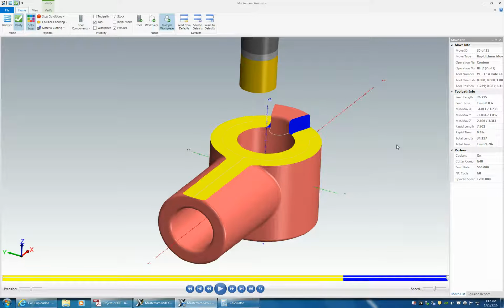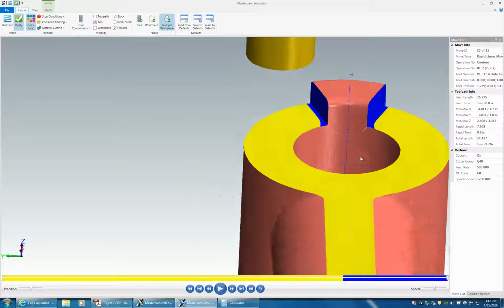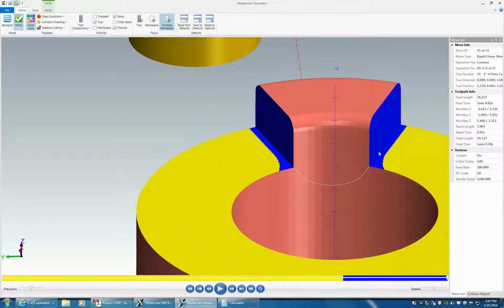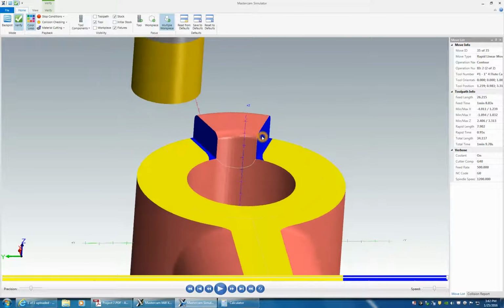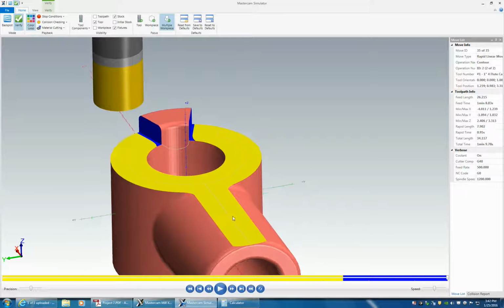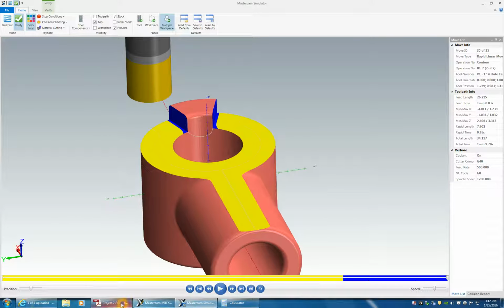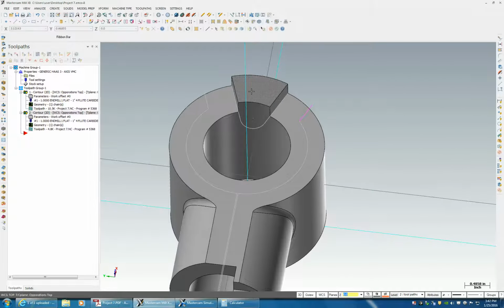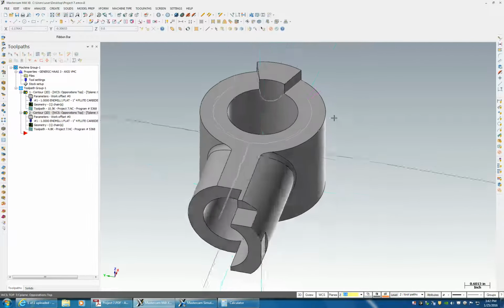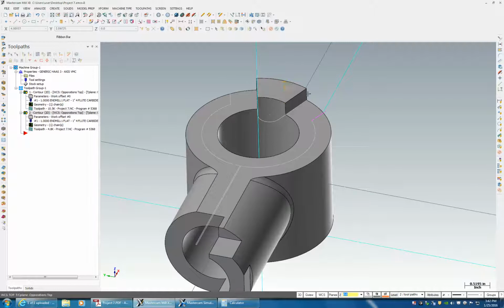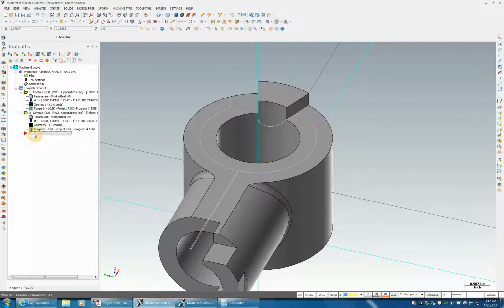There we go. So that's exactly what we're looking for. You can see where it had 50 thousandths material came through. Now we have this notch. Now let's see, there are a couple more operations we still have on the top. One is milling this top flat, and the other is running out this notch here. So let's go ahead and, while using the same tool, deck that off.